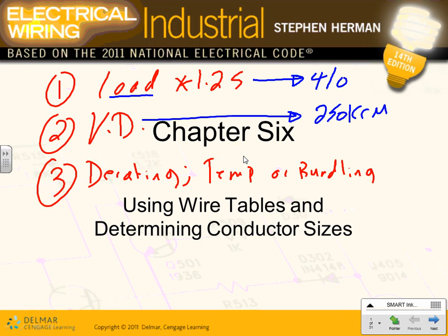So I have to derate, and to add insult to injury, you put them outdoors where the ambient temperature could be 110. So you have to adjust for that. On the roof, it's even worse, you have to add reflected heat. So suppose because of all this, you end up with 350 kcmil. Who's my genius that's going to tell me which size is going to rule? If these three calculations for the same load came up with three different numbers, which one are you going to pick?